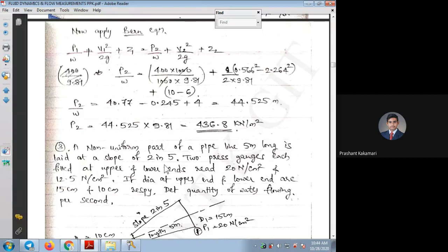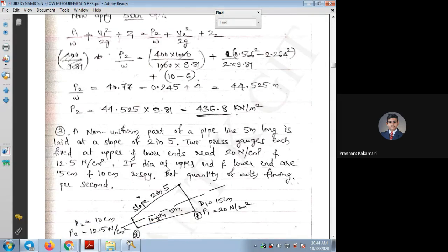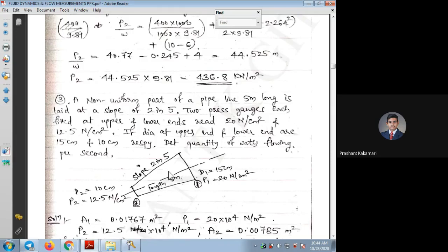So in such cases, we have to consider one end of the pipe at 0 point, datum 0. Is that clear? So in the sketch you can see whatever the lower point is there, the streamline or the flow line, the lower side point we have to consider 0 now because datum point is not given anywhere.